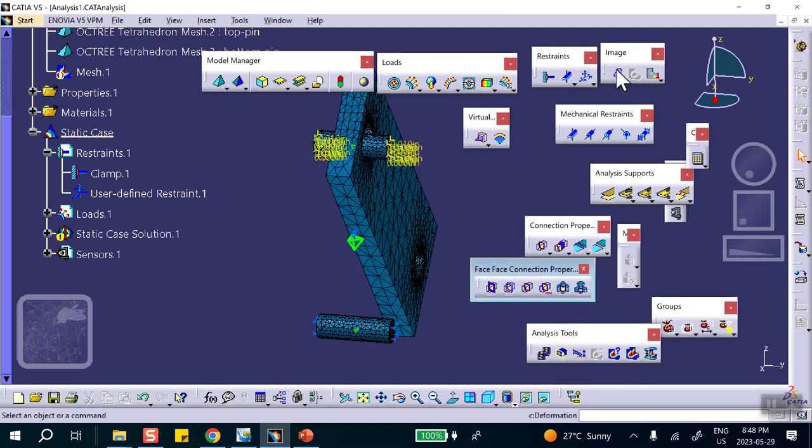So let's look at deformation. Now you can see that that pin is not going to move in and out or rotate, but the block has no idea that there are two pins inside of these two holes. Whenever you do assembly constraints, whenever you do assemblies, you have to say how the parts interact with each other.